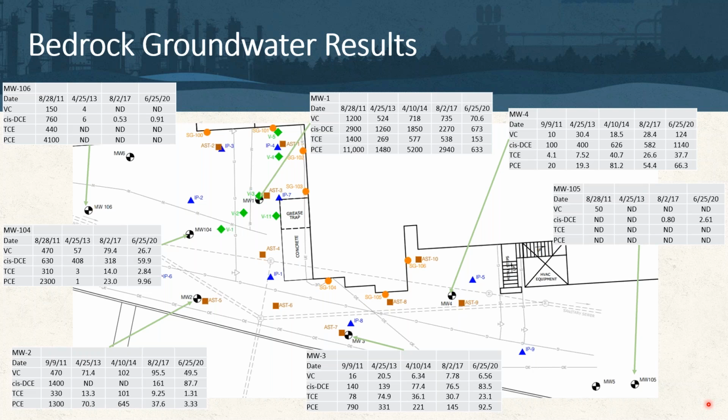Excuse me. So getting into some of the results and data over time. Again, this remediation project was initiated in 2011. So the benefit is that we've had almost 10 solid years of data that we can look at to show progress of this managed closure and the success here at the facility. So what we're doing here is looking at the on-site wells on the east side of the creek, the stream, which I don't know if it was clear from the previous drawings, but that stream is going to basically go from left to right across the bottom of the page here, from MW2 to MW3 box that you see right there. And what I want to highlight here is going to MW6 on the upper left-hand corner.